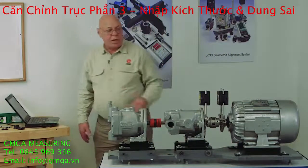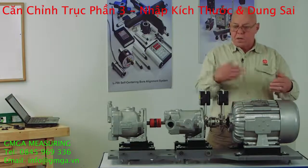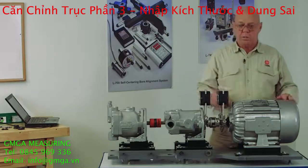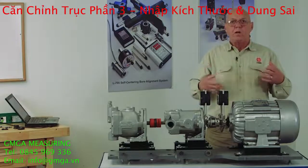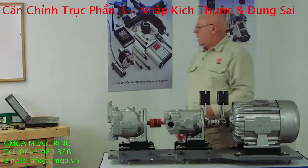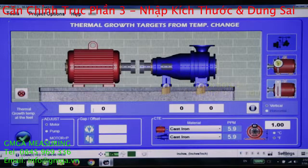I know what the thermal growth is at the front and back foot, and then that will calculate for me the temperature change, I should say. So I could measure this cold using a laser thermometer, and then run it to hot, and then I know what the temperature change is at the front foot and the back foot. And I could tell this by clicking on the temperature one. I could tell it what that change is, the temperature change.